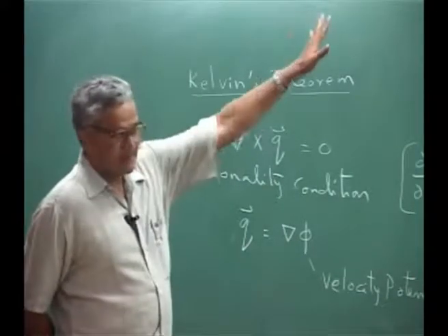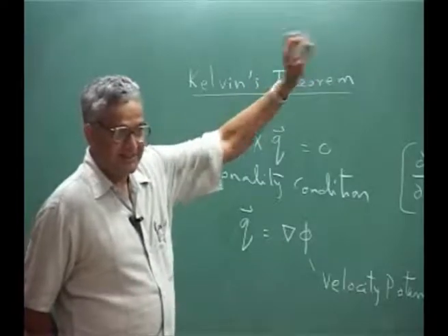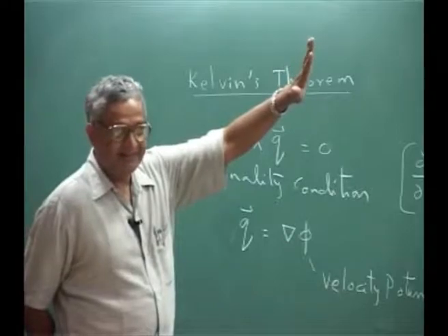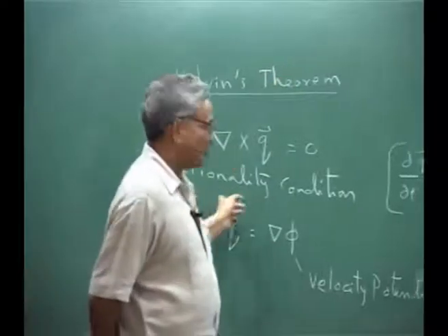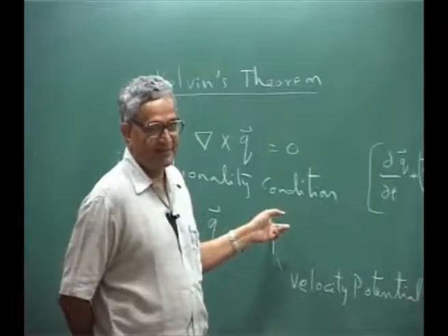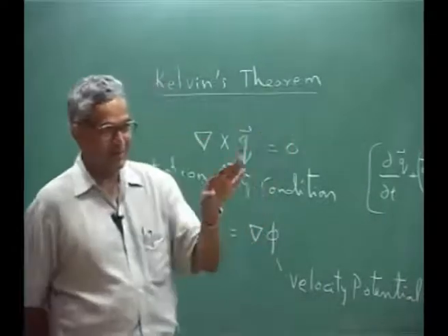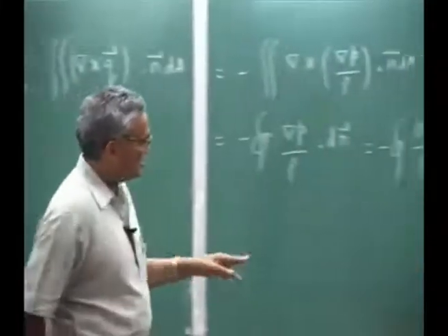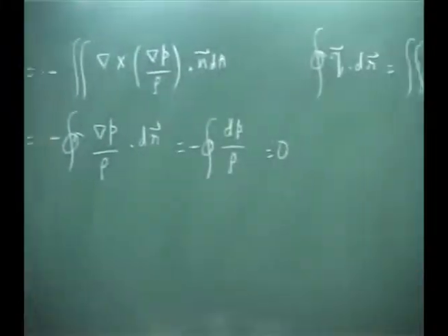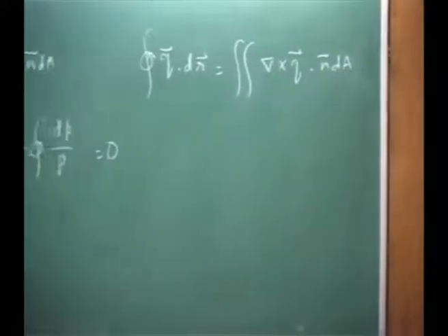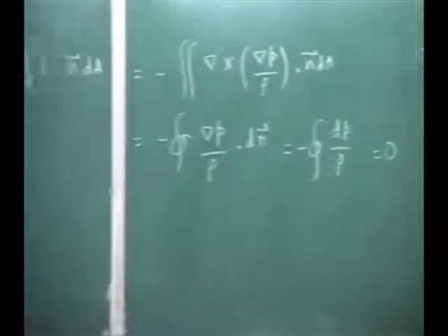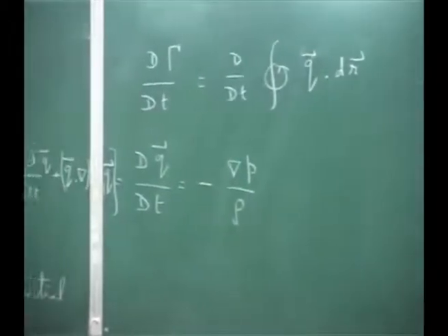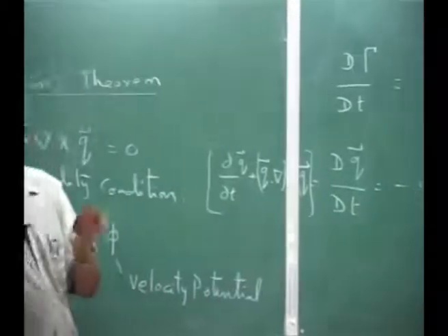So, you said first is inviscid, isentropic, then irrotational. Inviscid, isentropic gives you barotropic, that is pressure as a function of only density, through the relation P over rho to the power gamma is a constant.